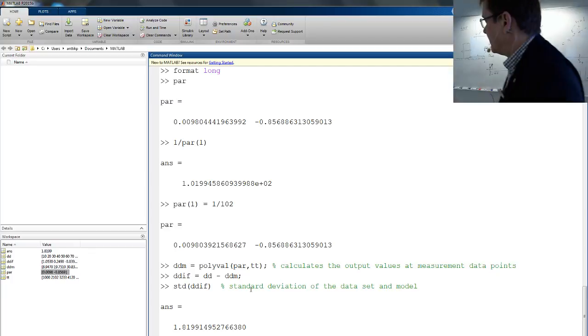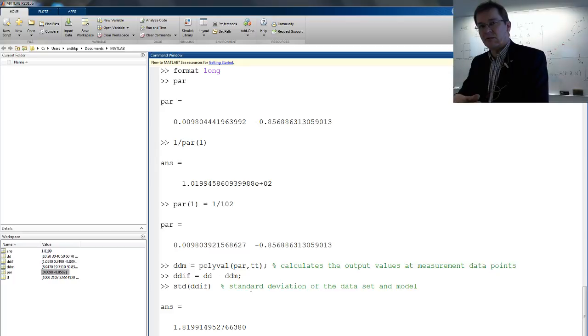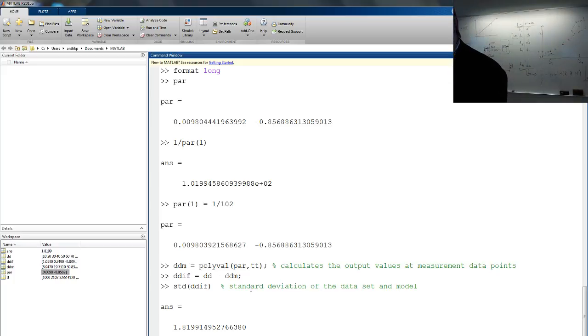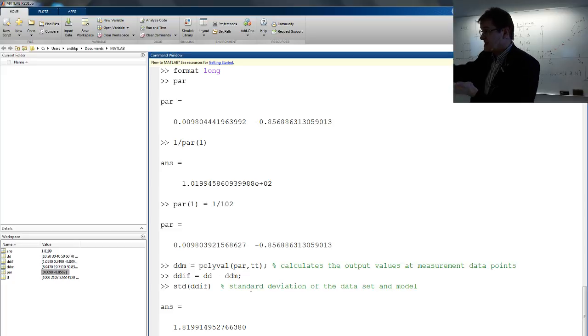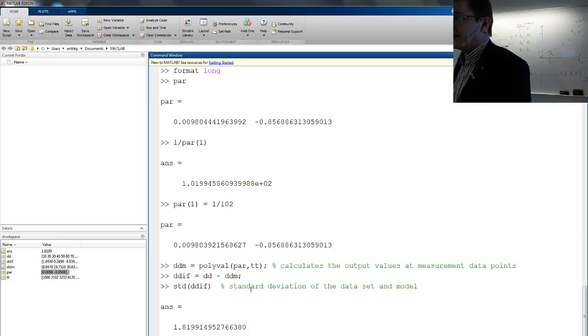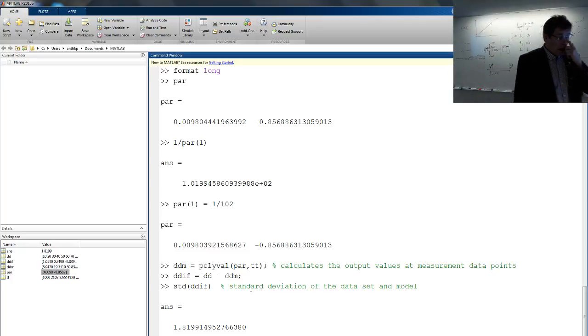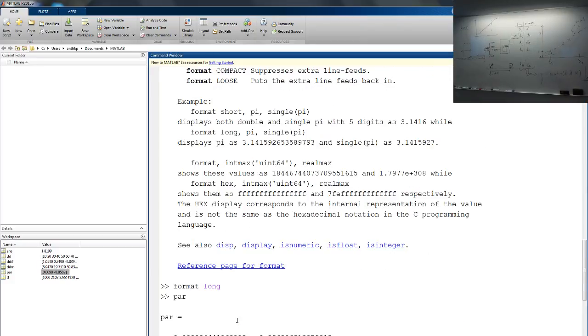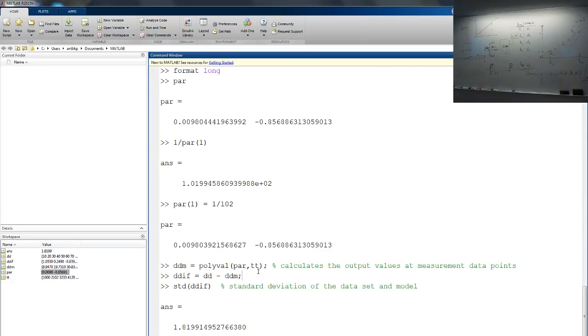Okay, so the rest of that is more like playing with the accuracy of your result, how to calculate an accurate enough value. So in this case, we do not need floating point on the microcontroller, since we can do this kind of integer tricks to calculate those. Okay, good.